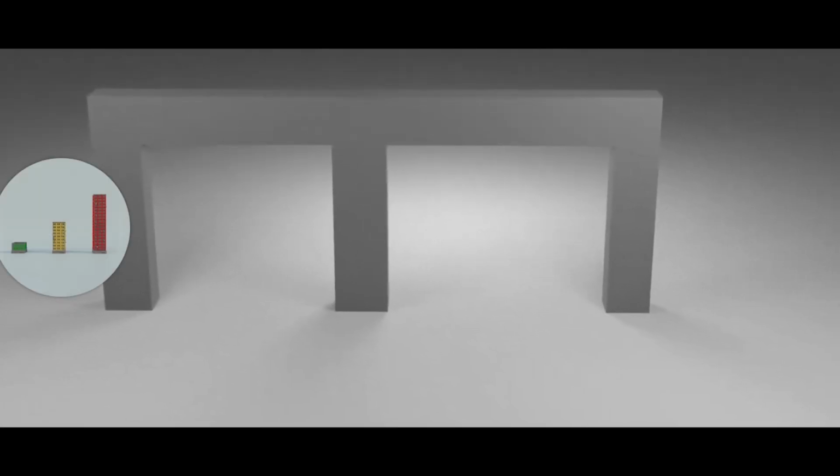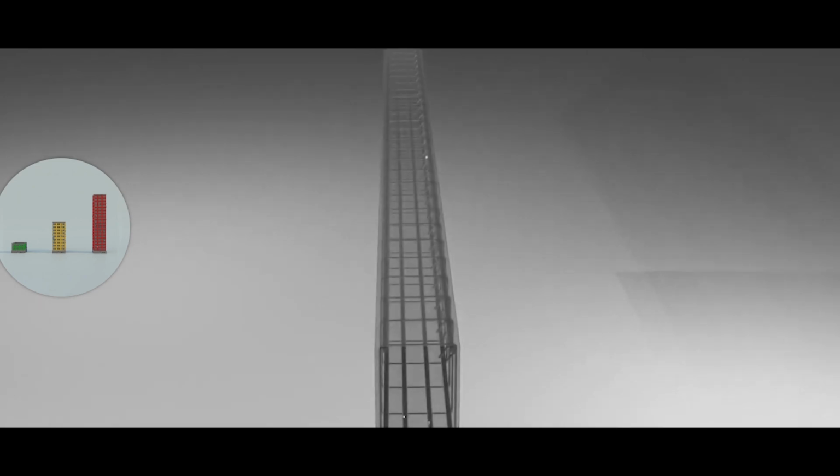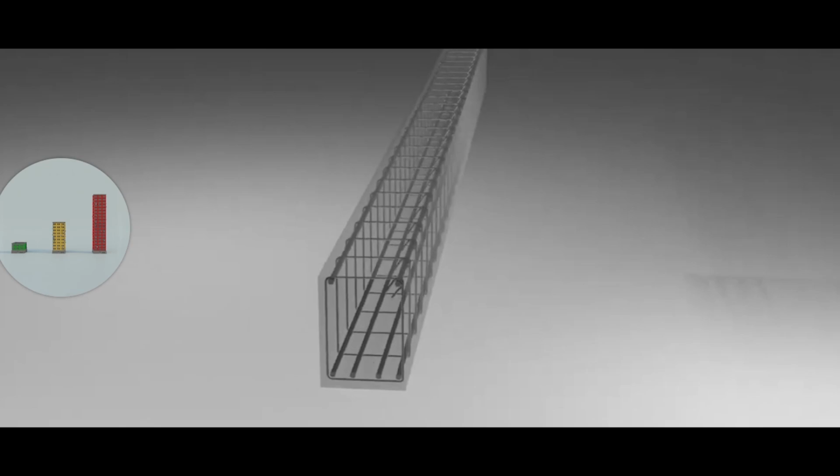When beams are subjected to loads, they go through different stress stages. At first, they are in the elastic stage, meaning they can revert to their original shape once the load is removed. As the load increases, yielding starts. When the entire cross-section yields, a plastic hinge develops. This marks a crucial point. If the load surpasses this threshold, the beam will fail.